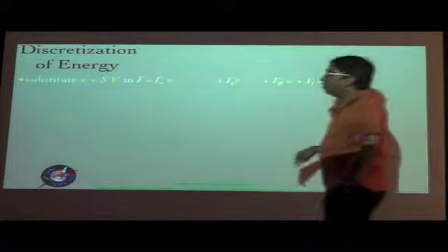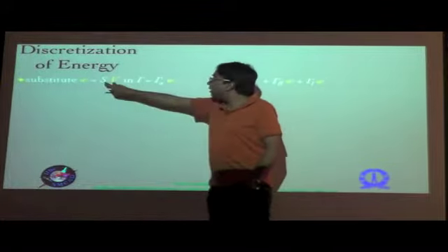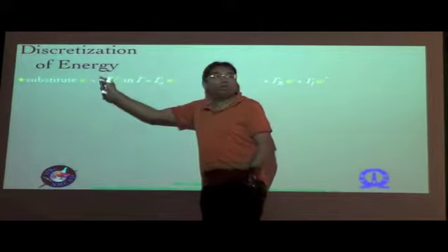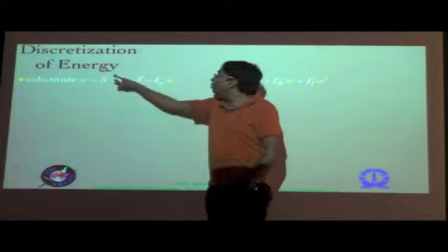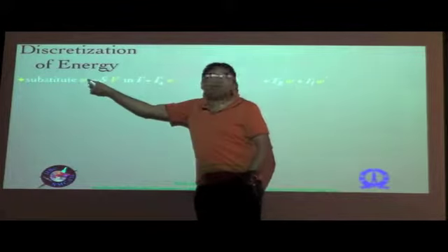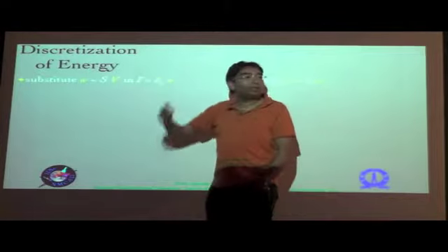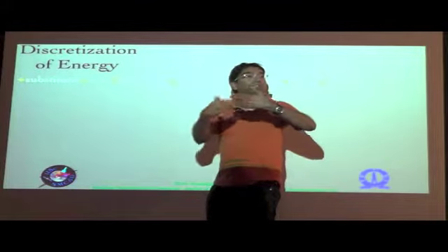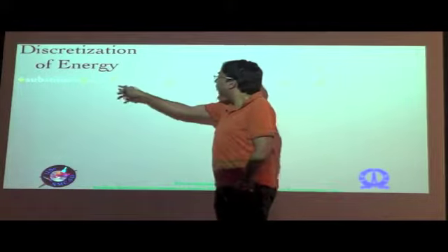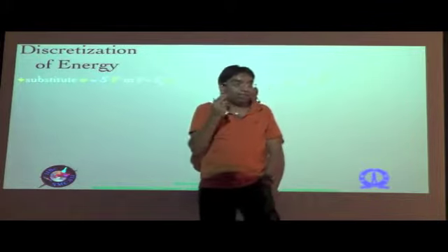Now, therefore W is equal to S times V, and in terms of the unknown quantity, it's basically V, because S are the assumed shape functions, so V becomes the unknown instead of W. So that's basically what we are going to try and determine now. Of course, it is the actual values at different points along the cross section, which are the nodes of the elements involved. Now we substitute that into the expression we have for the 3D strain.